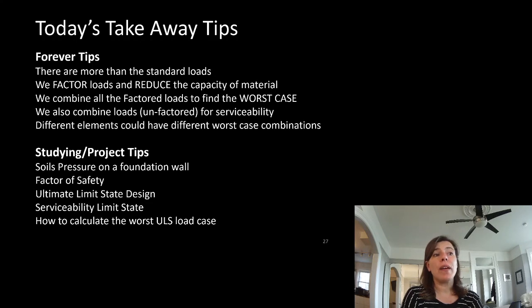You should know how to find the soil pressure on a foundation wall. You should understand that factor of safety exists, even though it's not what we do anymore. You should understand ultimate limit states design, or the factored load combinations that I showed you, and that serviceability limit states are essentially the unfactored versions of that, but snow and wind will have a different importance factor. And you should know how to calculate the worst ultimate limit states load case.